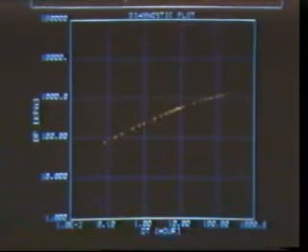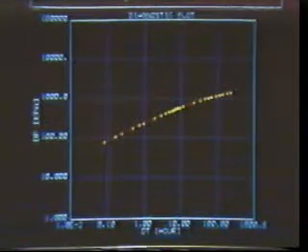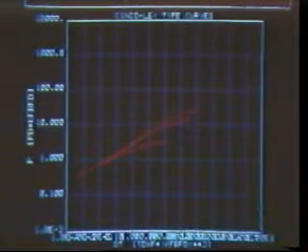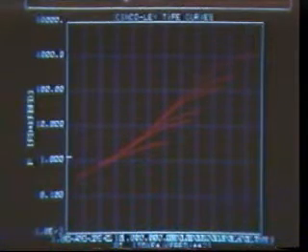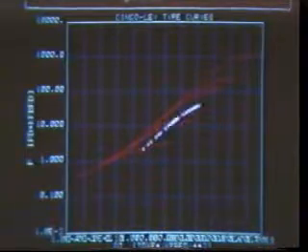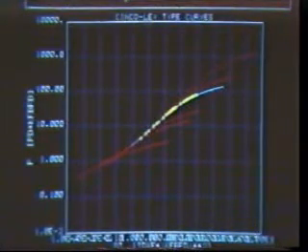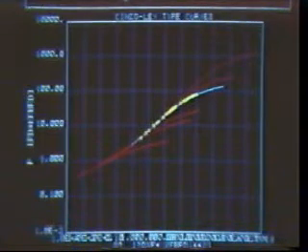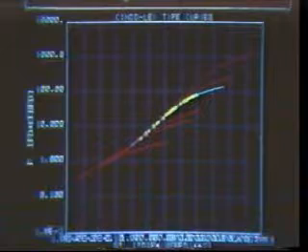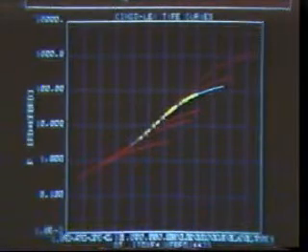Again, we see our data plotted in the form of log delta P versus log delta t. We select the appropriate type curve for our vertically fractured well, overlay our data plot upon it, and move it until we are satisfied that our match is correct. Note as before that the values of delta P and delta t, which are read directly off the log-log plot in the curve matching process, are not presented here, only the data points. The computer does all the record keeping for us. Having made the match, we obtain the corresponding values for p sub D and t sub D. At this point, we can now solve for k and x sub f using the appropriate equations.